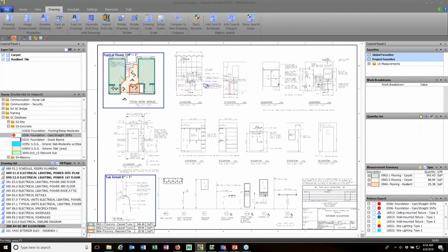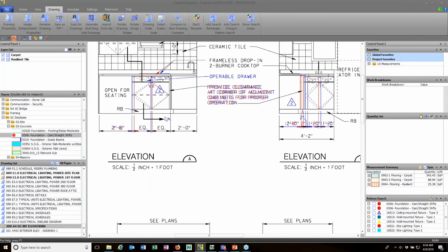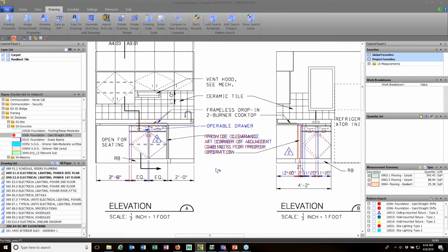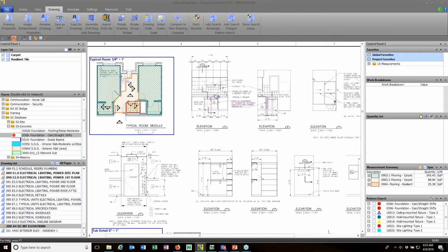Click OK and it brings it in. And so here's the changes. It highlights the differences for me. And so I can right click here and I can say, show me, emphasize just the new stuff. And the blue is emphasized and the red's still there. It's just not as intense a color. And then I can come back, show the old and the new. So it's going to help me find changes.